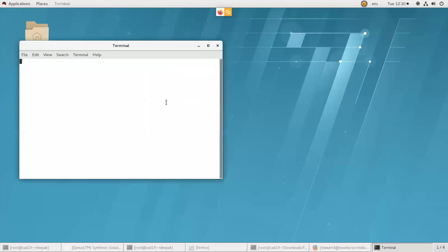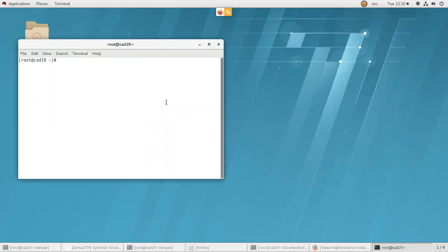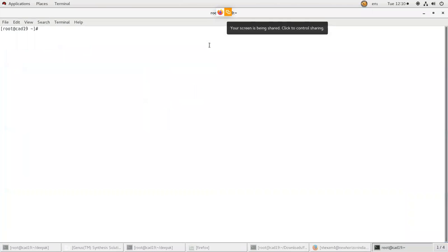First, open terminal. After that, first source your cadence tool. The procedure for that is press csh. That will open the C shell. After that, press source /home/install/cshrc. You will get like this: welcome to cadence tool.